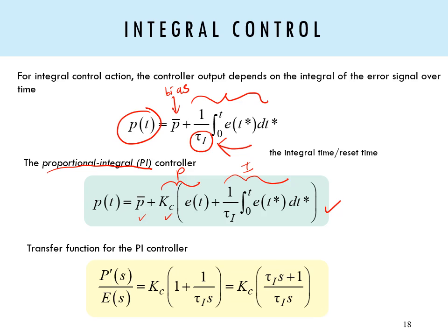Under the PI controller, as long as the error is present, the controller keeps changing its output, integrating the error. Once the error disappears, which is when it goes to 0, the controller does not change the output anymore, whereby it integrates a function with a value of 0.